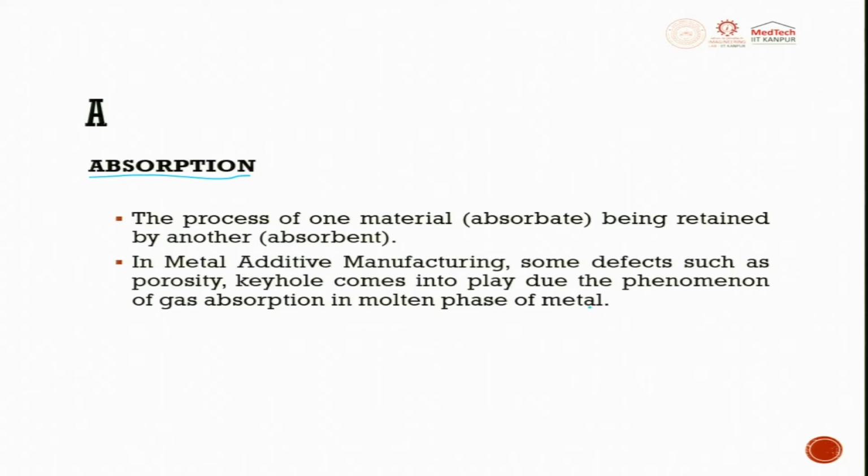So, in the last lecture we saw there is the DED process, and the other one is the PBF process, powder bed fusion, and directed energy deposition. In both cases, you start with a powder, this powder will be melted and then tries to fuse with the neighboring powder. While doing so, if it absorbs or if there is adsorption of oxygen on the surface, then that will lead to gas absorption.